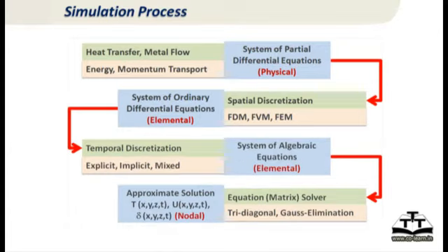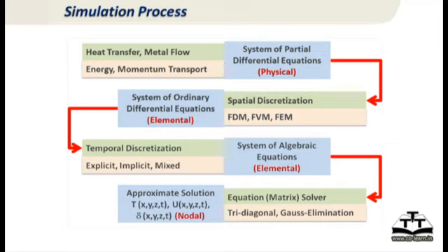Now you can divide the time in different ways and compute it in either an explicit or implicit or a mixed kind of method. So this is FDM, the finite difference method, FVM, the finite volume method, FEM, the finite element method. In a way, what I showed you earlier, the structured mesh is typically FDM, the unstructured mesh is typically FEM as a starting point. Then we solve the equations in some computation method.